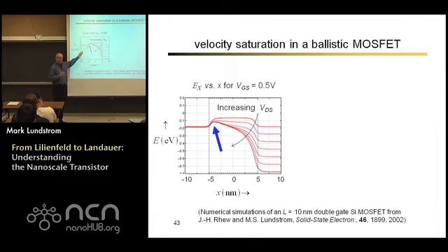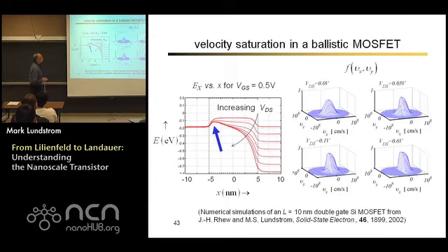The charge here, if the transistor designer has done his or her job well, is Cox (Vg minus Vt), just like it is in a classic MOSFET, even though this thing is really small and the electrostatics is two-dimensional. If you've done things right, the charge is Cox (Vg minus Vt). So then the question is, what is the velocity there? Charge times velocity is current.